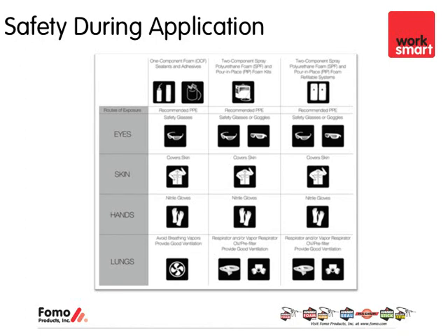And during application of both these, the required PPE, again, would be protective eyewear. You want to cover your skin. You want to have nitrile gloves for your hands. And in this case, you want to use organic vapor respirators and make sure that you've got proper ventilation when you're installing. These are all very important recommendations that we want to see happen as far as utilizing these products in applications, particularly as it relates to the weatherization applications that we're talking about today.